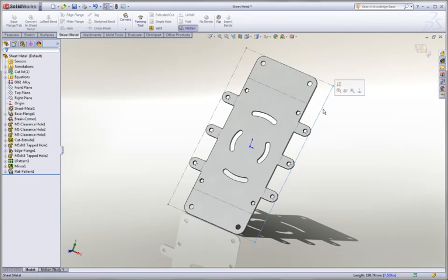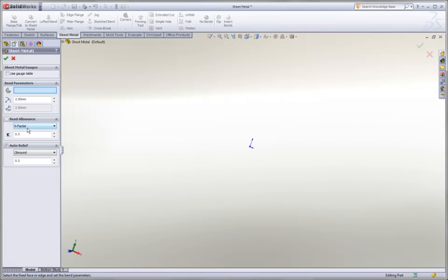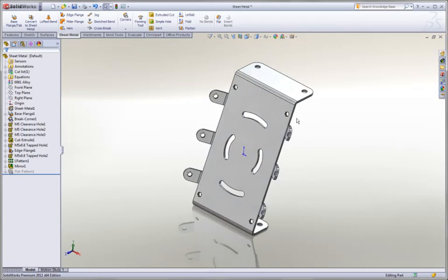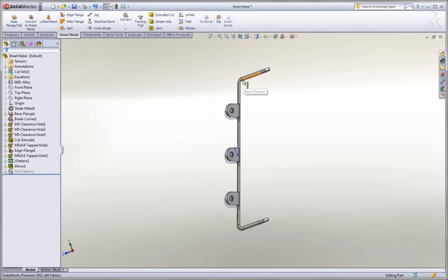What I want to specifically focus in on is the length of this. This thing's 190.74 millimeters long. We can see that down in the lower right hand corner. And that's calculated based on K factor. K factor basically selects a neutral plane along the sheet metal and it unfolds it. The problem is that can create some issues when you have bends that go over 90 or are not quite 90, and you get all these unique bend scenarios.